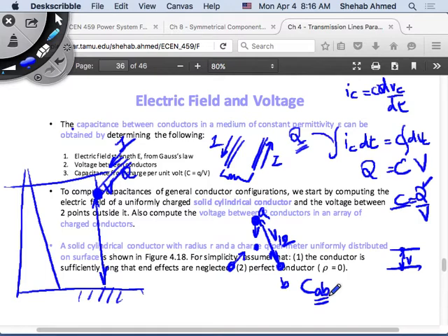What do you typically need to build or to solve three-phase balanced power systems? You need the single-phase equivalent circuit, right? So I would need the single-phase equivalent capacitance. If I know my voltage between two lines, I know there's a relationship between line voltage and phase voltage, and if I know that relationship, I can calculate the capacitance in that case as well.